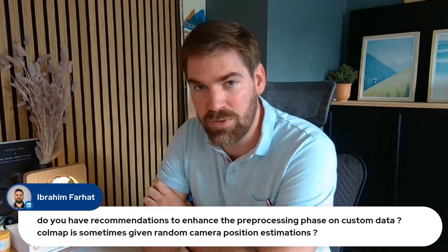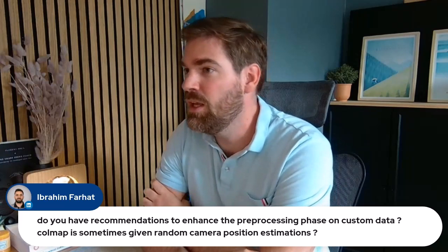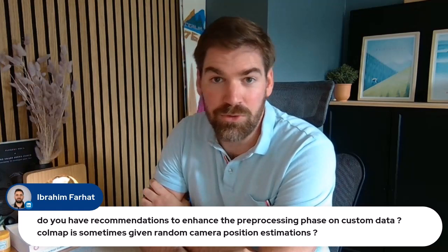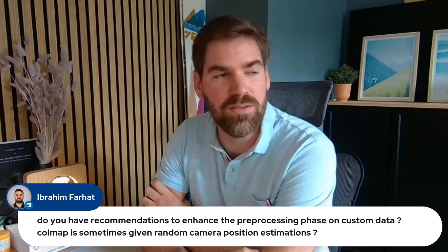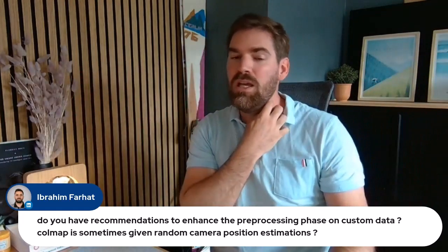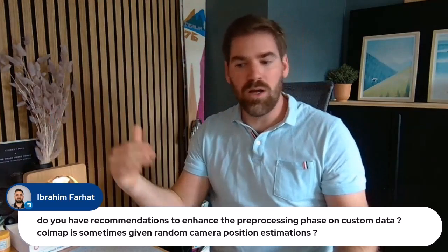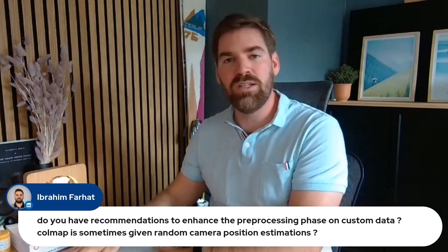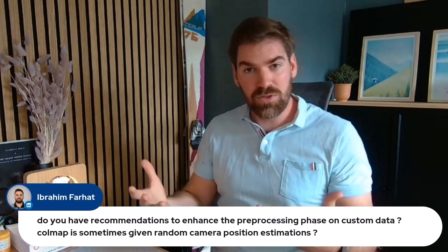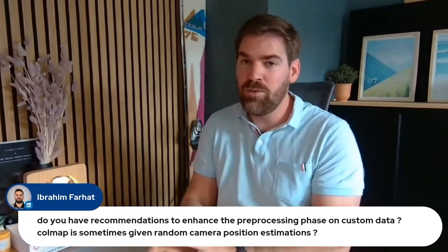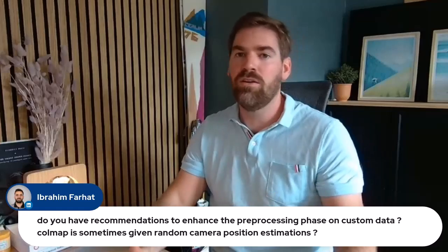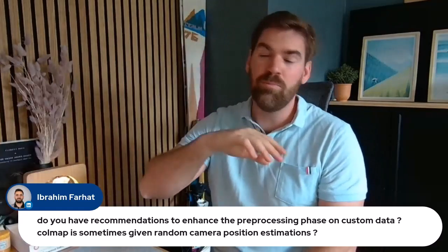Not only SIFT, but SIFT, SURF, and ORB would be good. If this does not work for you, of course, play on the acquisition phase. Make sure that your acquisition is well organized for a photogrammetric process. If not, you move on to Metashape or RealityCapture, and you export the pose images. You can do that in both, and you use that directly within PostShot or any other Gaussian splatting software, or within Python.